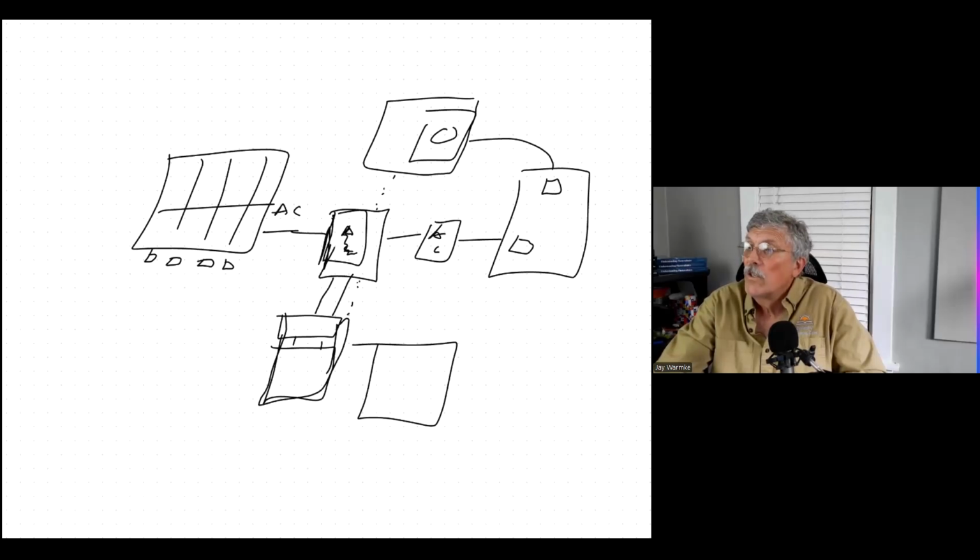So all of these things are communicating to each other. Let's say that the grid goes down, there's a power outage, and you want to use the battery storage. Well, the meter collar is now going to disconnect from the grid. It's going to isolate your whole system from the grid and tell the system it's now working in standalone mode.